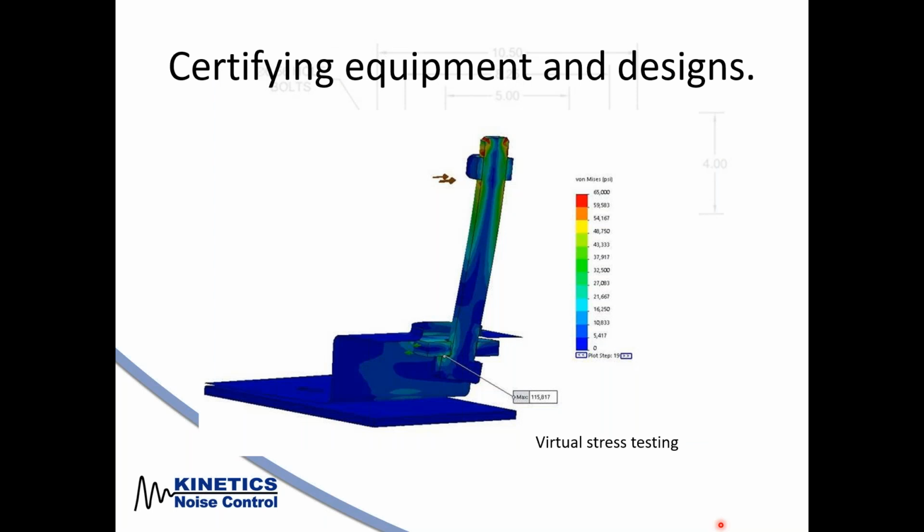And also, we do virtual stress testing. So, for instance, fan manufacturers have come to Kinetics, and we've taken their equipment, put it in a 3D model, and then stress tested the equipment itself, and then offered a seismic rating based on the stresses that we can do through virtual stress testing. This saves the manufacturer having to send that equipment off to have it put on a shaker table and tested for seismic forces. So that's the end of the webinar.